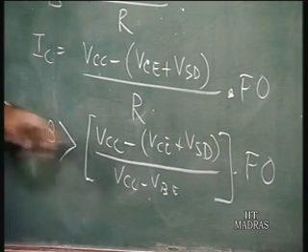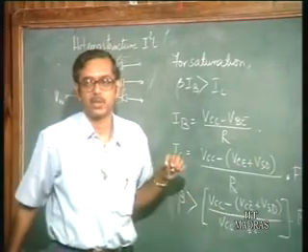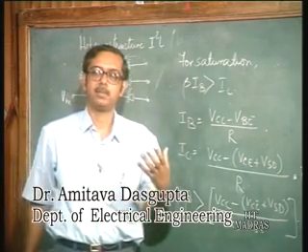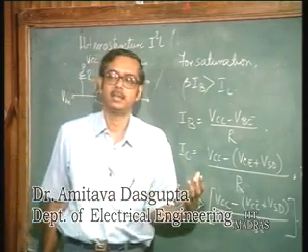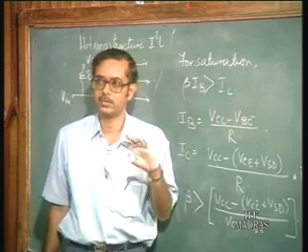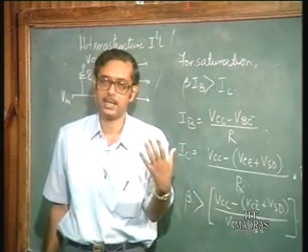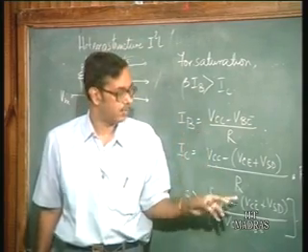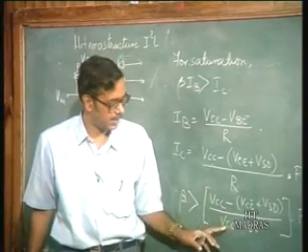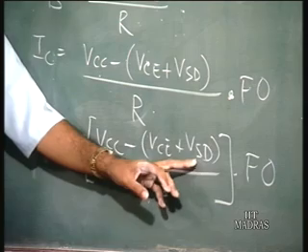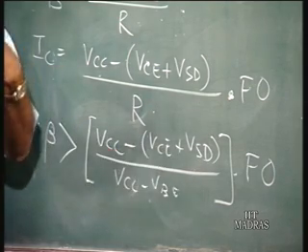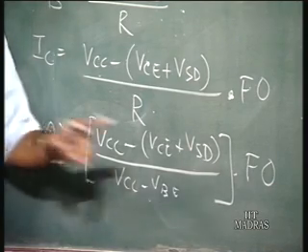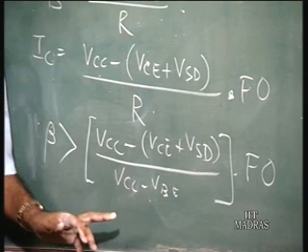And what are the different voltages? Usually, in heterojunctions, as I said, you have aluminum gallium arsenide and gallium arsenide. The band gap of gallium arsenide is 1.42 electron volts compared to 1.1 for silicon. Aluminum gallium arsenide is much larger, almost 1.8 electron volts. So, these voltages VCE, VBE and even VSD, that is the Schottky diode on gallium arsenide, the cut-in voltages of any junction depend on the band gap of the materials. So, these are going to be much larger compared to that of silicon.